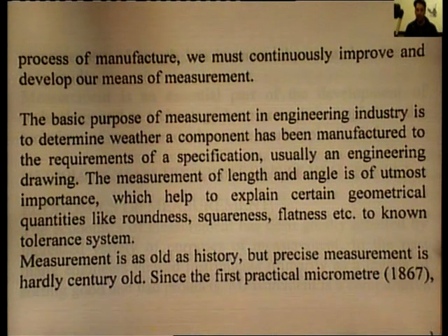The basic purpose of measurement in the engineering industry is to determine whether a component has been manufactured to the requirements of a specification. Usually an engineer, from the engineering drawing, the measurement of length and angle is of utmost importance, which helps to explain certain geometrical quantities like roundness, squareness, flatness, etc., to a known system of tolerance.